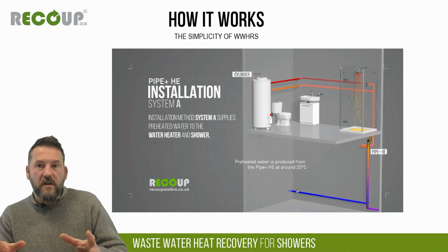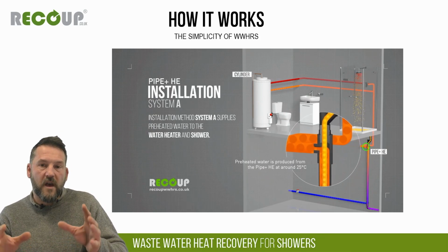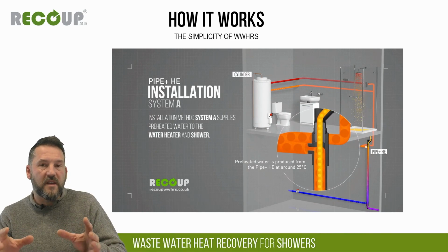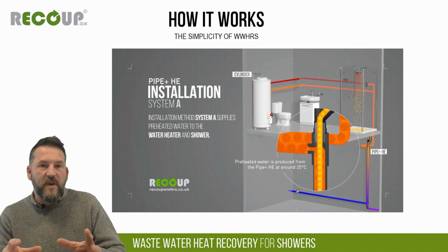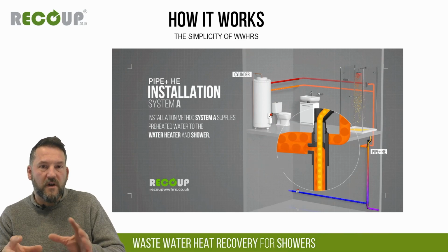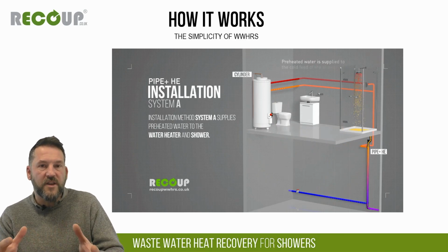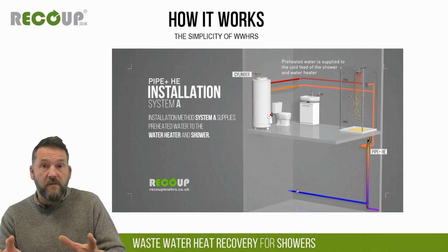So in the example we're showing here at standard shower rates, that cold water main coming in at about 10 or 12 degrees would normally expect to be preheated up to about 25 to 28 degrees. So it's a big free energy uplift of around 15 to 18 degrees. And that's the basic premise of wastewater heat recovery, all products, all types.